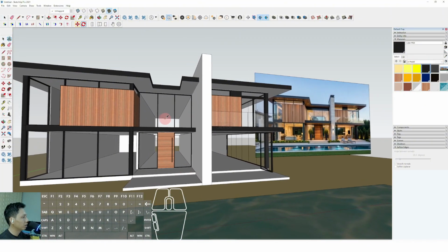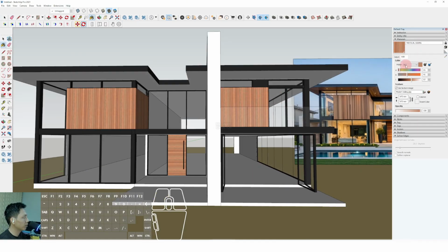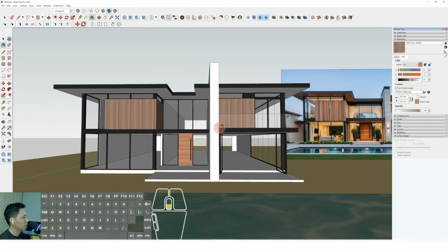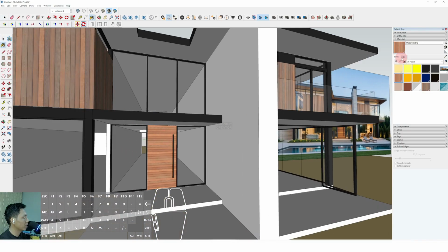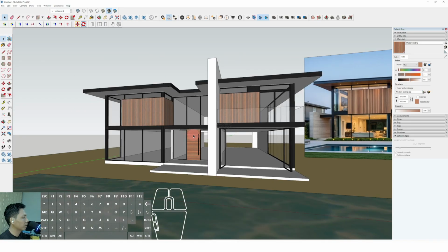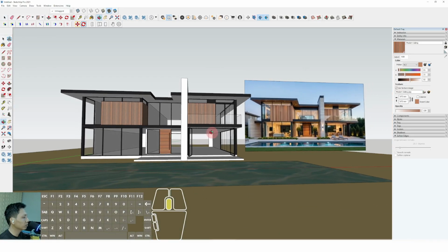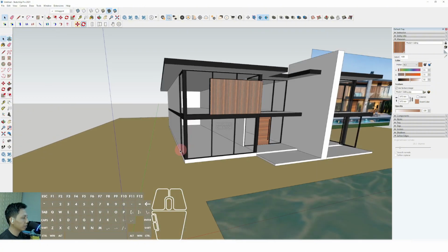Okay, we can click pick point materials and click this materials and edit, and we can set the hue, light, and saturation. And you can set the saturation and set the darkness like this to make it more dark. Okay, then we can select these materials and edit, and we can assign the materials like this. Okay, now we can make the another elements.